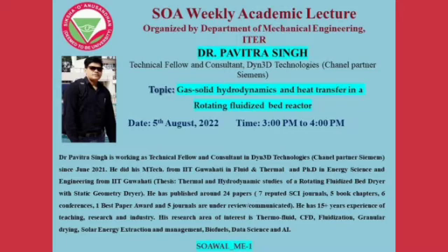So you can see in this figure, in the free bed region the volume fraction is almost 0, and in the solid bed region variations are minor. Actually when the air is entering this reactor, the volume fraction suddenly decreases because of the impact of air. Again it increases in the bed thickness of 112 to 116 mm. Again it decreases in the bed thickness of 98 mm to 112 mm.